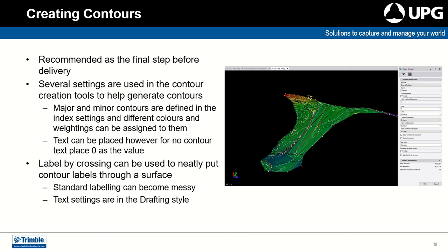In terms of the label text style, this is defined in the drafting tab as one of your default text styles, and you can choose that parameter. I would recommend making sure that your text styles in TBC are the correct height and type before embarking on this process. However, if you need to edit these options on the fly, the text will be updated against what has been done down the track. So all the elements that are created in TBC are dynamic.